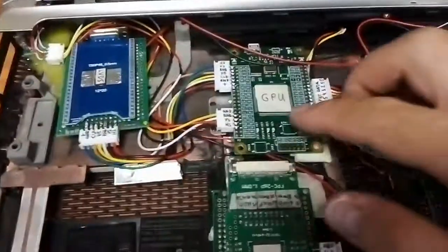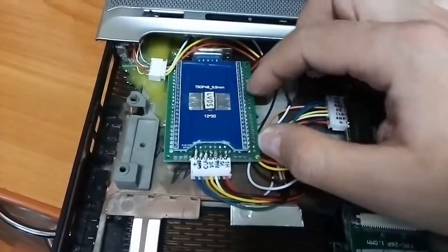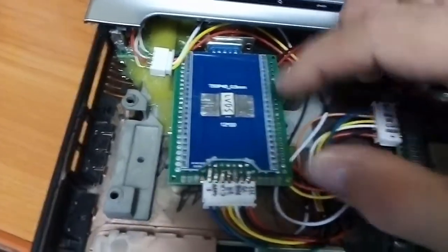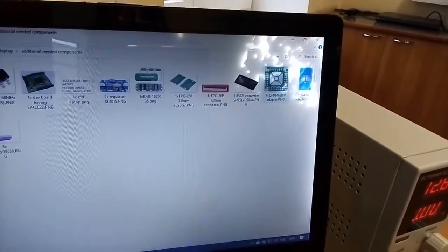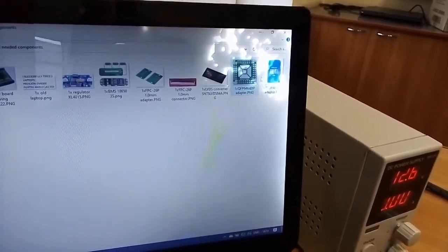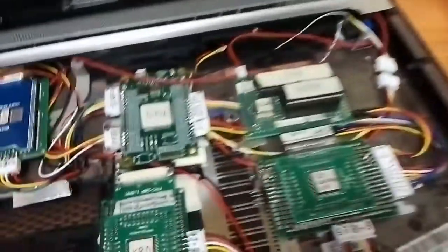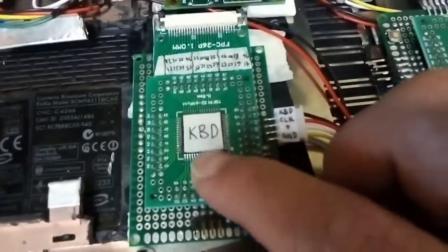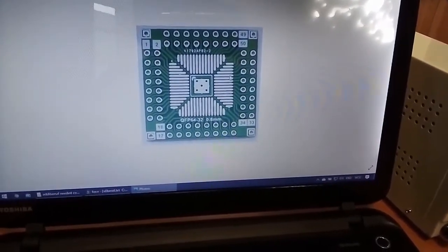and boards. For that we need also an LVDS converter that sits on the DIP, SOP to DIP converter, and that's on a board similar to what we used already. That's for the controller, Atmega controller. Same. Since these chips are not standard, they are with small legs, and these legs are too many, and they don't fit in this regular DIP. They are not DIP packages. So we need a converter.